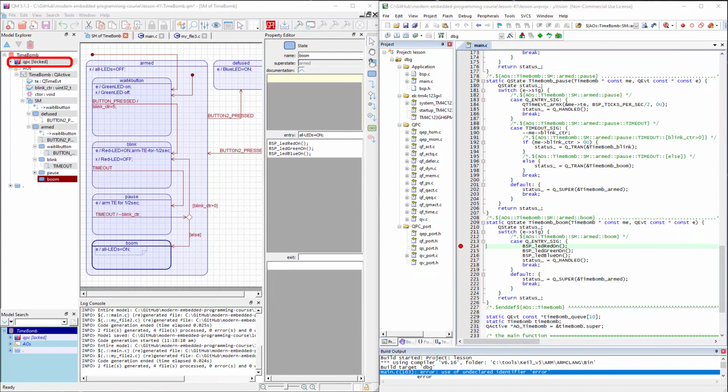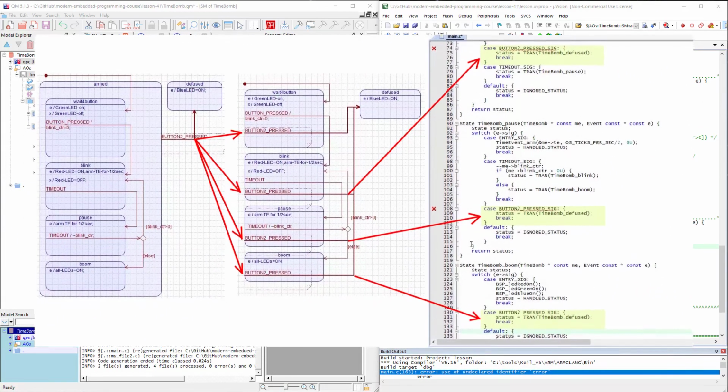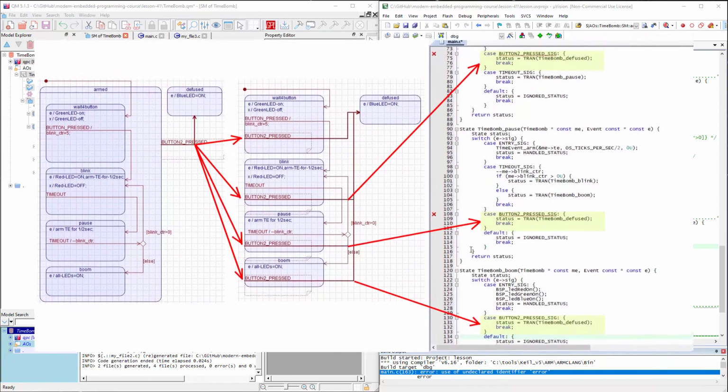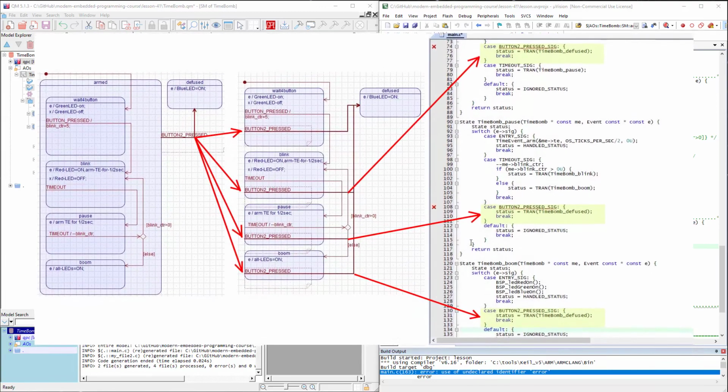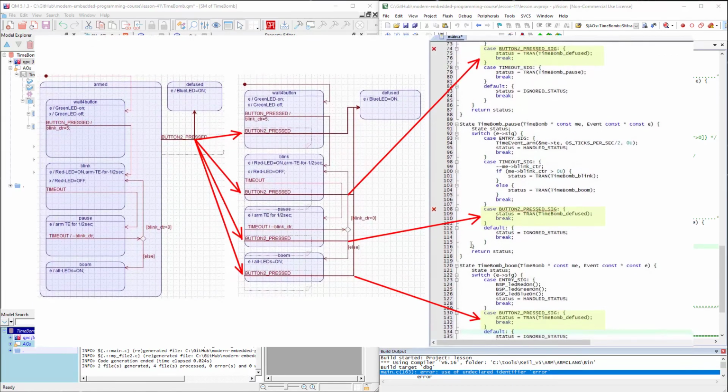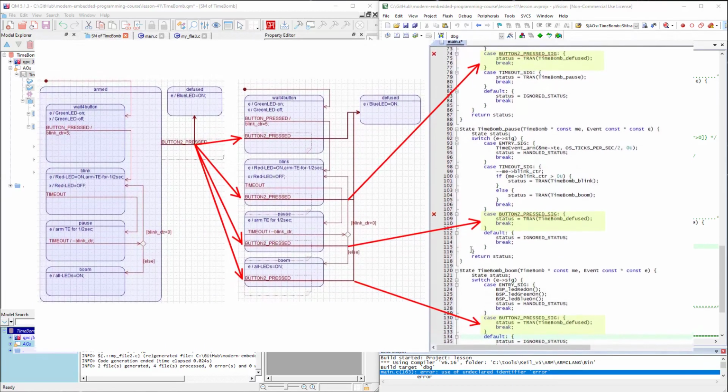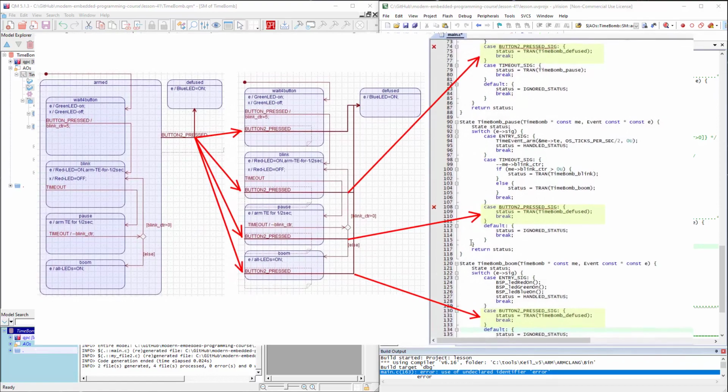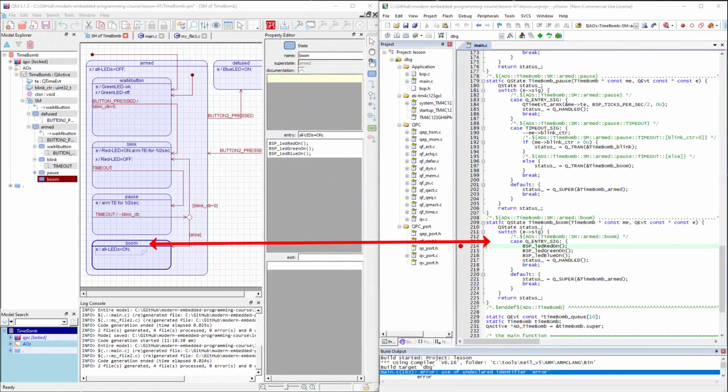Such traceability is not a given, and many other code generators don't produce bidirectionally traceable code. For example, some code generators transform hierarchical state machines into classical, flat state machines for implementation. This, unfortunately, brings back the repetitions of transitions, which hierarchical state machines were exactly designed to remove. In that case, the traceability from the model to code is destroyed, because a single transition in the model can map to several transitions in the code. Yet, the bidirectional traceability is a very desirable property and is actually required by various functional safety standards.